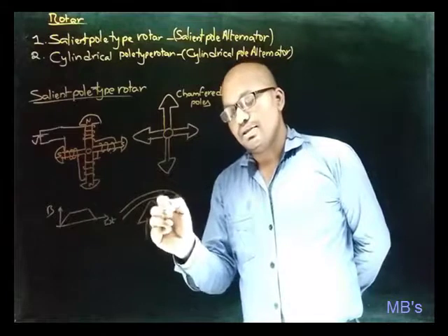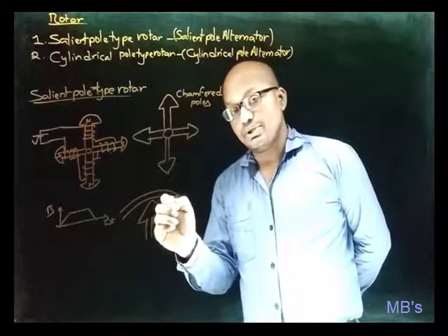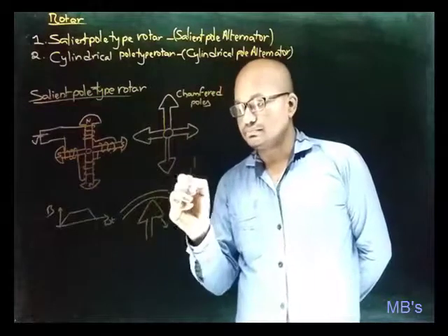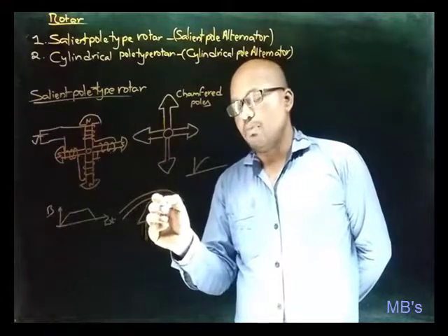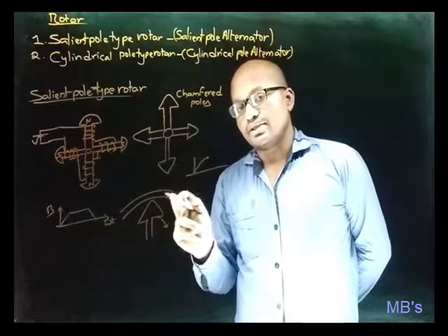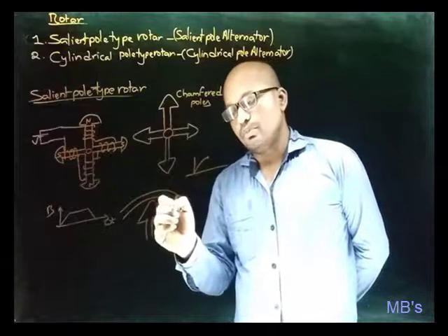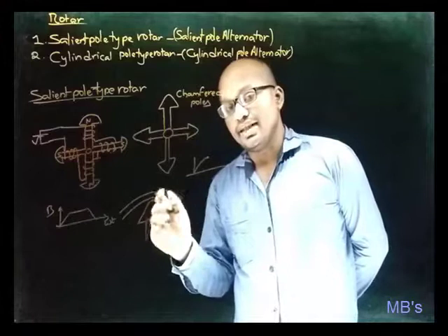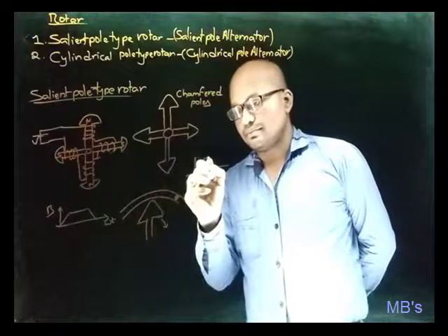So here, as the pole tip approaches the conductor, air gap reduces. As air gap decreases, flux will increase, like this. And upon reaching the tip here, then the flux will be maximum. And next, when the pole tip crosses the conductor, then observe the air gap will increase. So as air gap increases, flux will decrease like this.